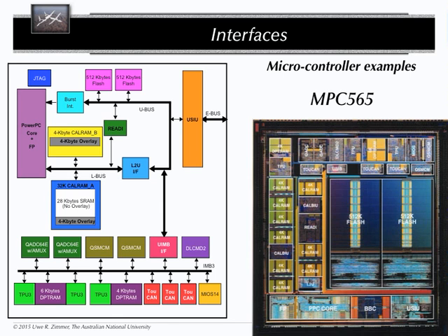So we are all happy at the moment that every semi-upscaled microcontroller will come with a floating point unit on it as a hardware unit, which relieves you from a lot of trouble, because now you have your floating point operations at the CPU clock frequency, at least basic multiplication. And you also know that unless somebody messed up some tiny detail in the hardware controller, which is way more rare than messing something up in your floating point library, you don't have to worry about the precision and the dependability of that thing anymore. Beautiful.